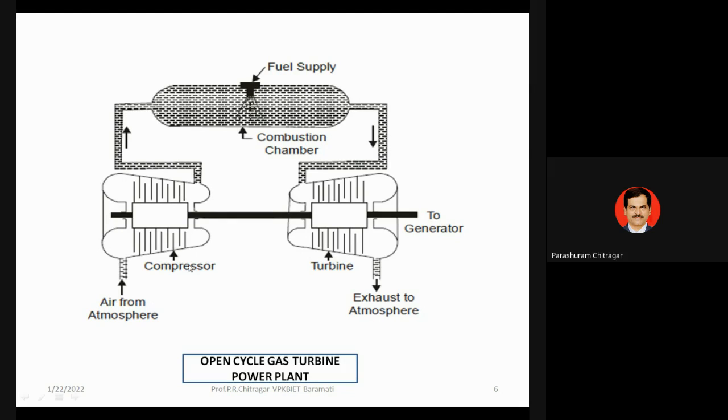So in total it is now 1 kg of air and 10 gram of fuel, together 1.010 kg. That gas is expanded in the turbine. Very small amount of fuel is added over here. So majorly, while explaining, we say it makes use of only air, which is a large quantity of 1 kg, and then it is sent to the atmosphere.